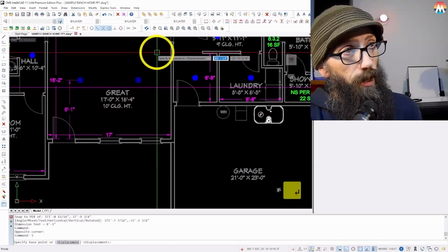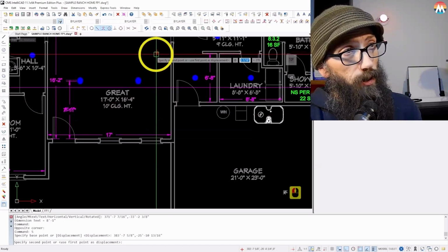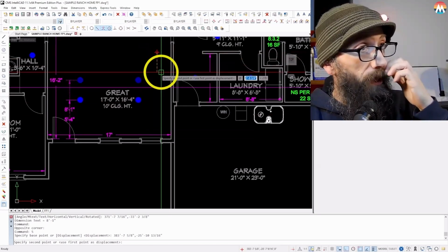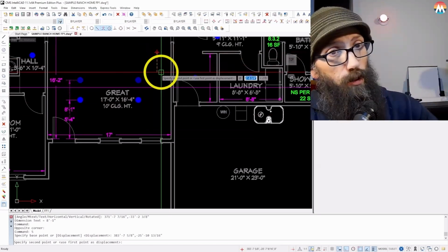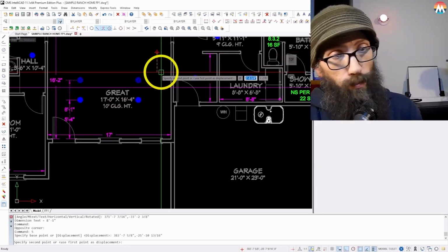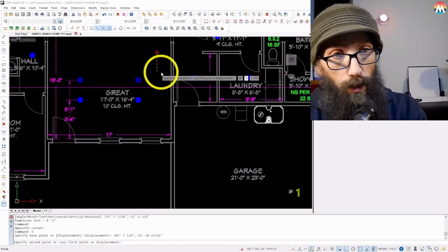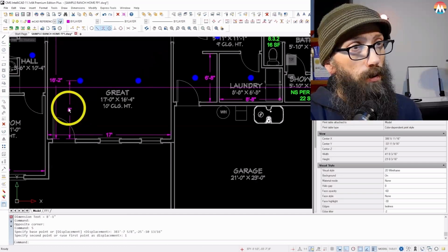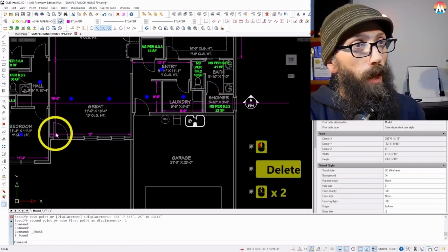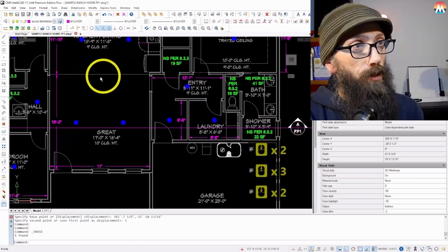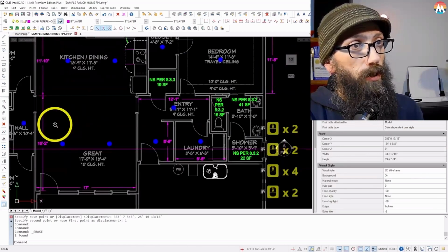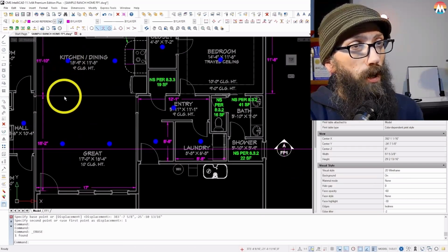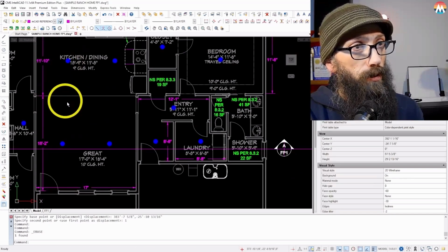And I'm just going to click out in space now with a blank area. I know I want to go down. I have ortho on, so it moves in a straight line, and I need to go 1 inch. I've moved it much further than that, but I'm just moving it in the direction, and then I type 1 for 1 inch on the keyboard, enter, and now it's 8 feet from the wall. And again, it's 2 inches from this change in ceiling elevation, but this sprinkler is at a 1 foot lower ceiling elevation and is completely covering this space.